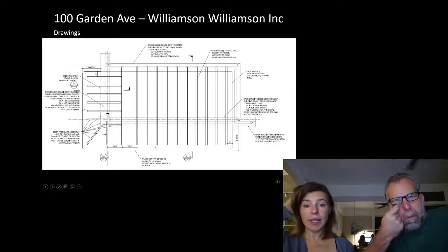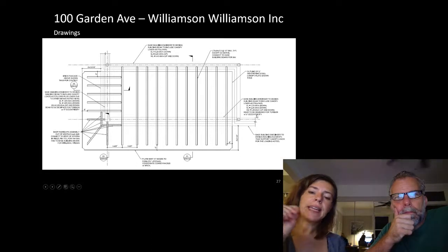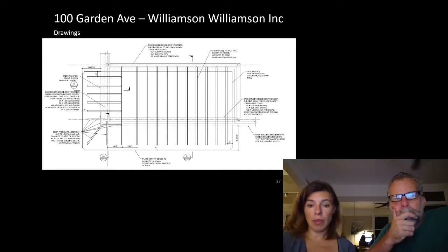So this was not designed by me. You can see that I provided them with the loads that they need to check. They would have done a preliminary design assuming something, but they don't know, is this supposed to be moment connected here? Is it something that's going to have a backspan? So you can see all of this is our cantilever zone, and these are all backspan elements.